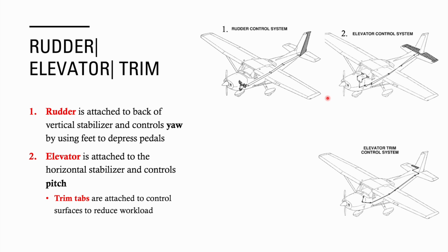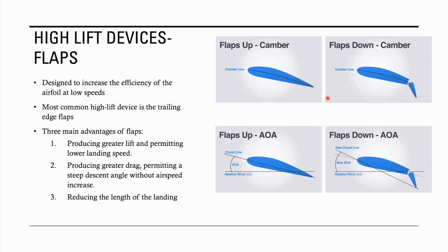It'll make it a lot easier because most of the time you're only flying with one hand. So you want to fly in the left seat with your left hand so it frees your right hand for radios, for throttle, things like that. So this hand is free to do whatever you need it to, and you control the plane just with one hand. So you can turn it, change the pitch. So try and get that habit as well. And if you feel like you have to fight the plane too much, you can just use some trim. It'll make your life a lot easier. Most people want to double hand it, and that's another habit to break.